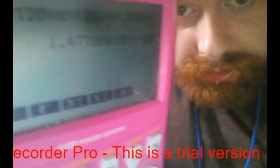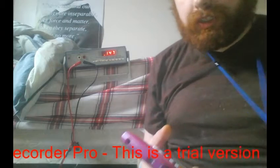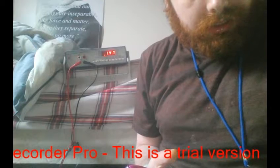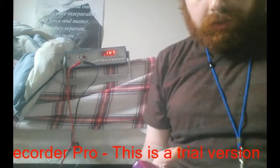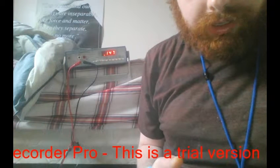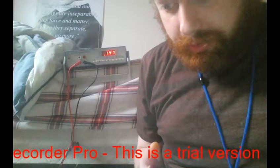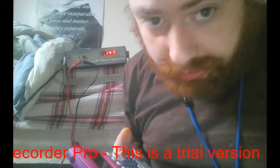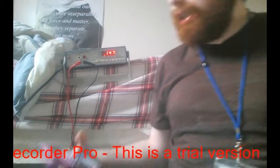In the scientific notation, the exponent is -8, which I think is correct for nanofarad, because exponents 1 to 3 would be millifarad, 4 to 6 would be microfarad, and 7 to 9 would be nanofarad. Yeah, that's correct. Basically, we're measuring the current, doing Ohm's law with AC reactance.